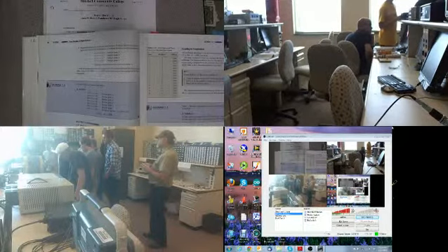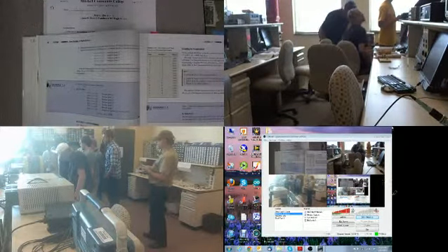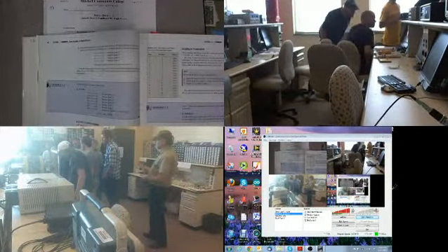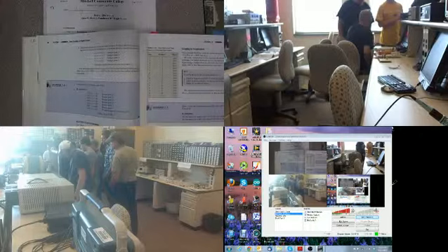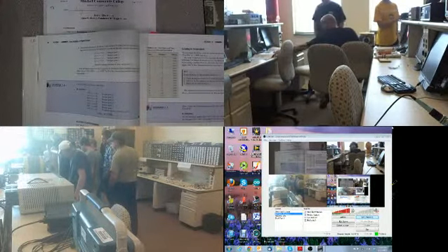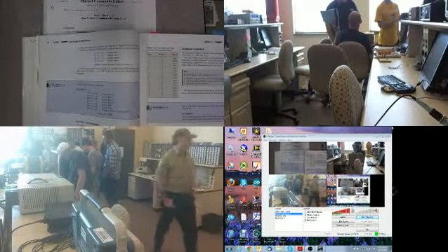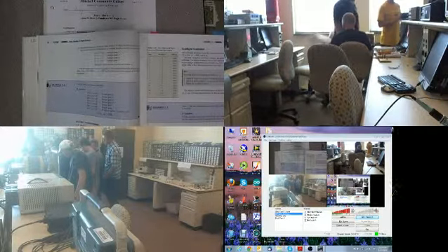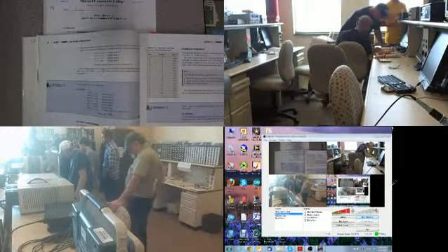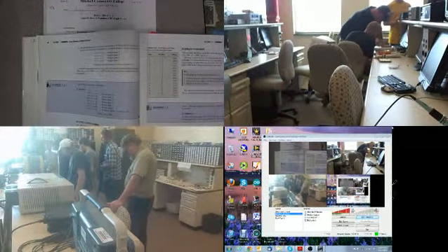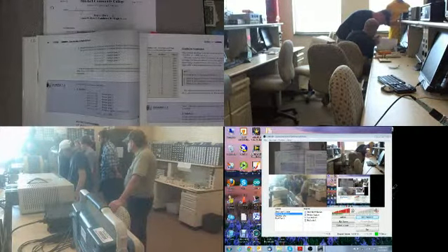We'll call this one U1B. If we use that one as U1A, then if we go in sequence of the numbers, this one would be B. So we're going to label this one B. And then since I used this part of the gate, that's pin 4. Does everybody see that? I'm going to put a 4 there. Now, what pin is this one right here? Anybody tell me what pin that is? Pin 5. Does everybody see that? Now the output of this goes to 6. So this is going to be labeled 6.